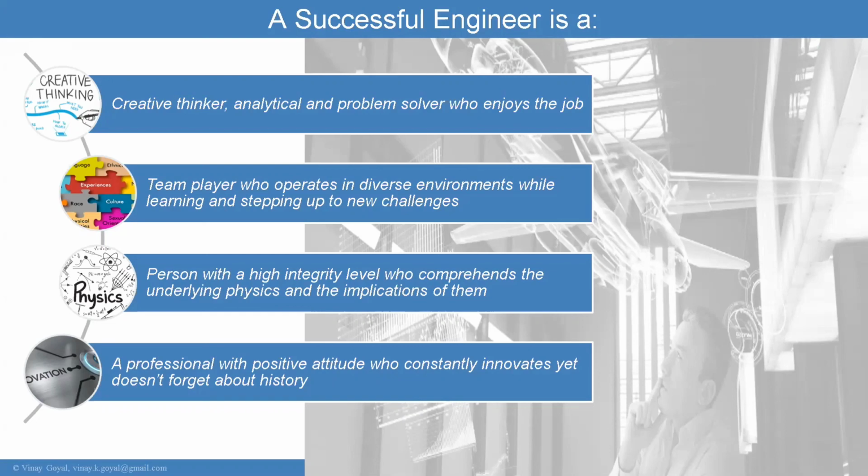I talked a little bit about calculation, simulation, and testing. To me, they have to happen in that order, right? When you are in the very early stage of the design and you're just sketching a concept, run some calculations, have that level of feeling on whether what you're thinking is feasible, and if it is, what are the implications, what are some of the points of attention, what are the things that you need to refine, what are some other things that you might need to do a little bit more research on.